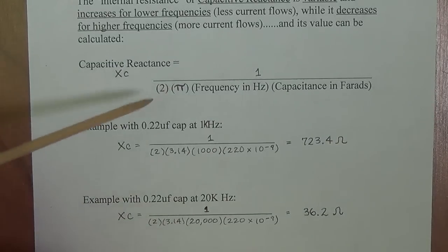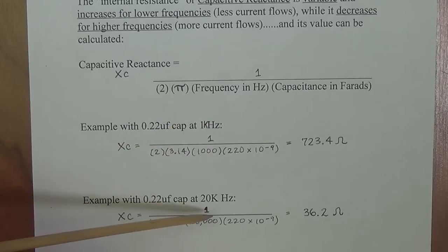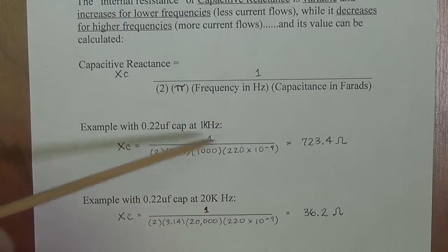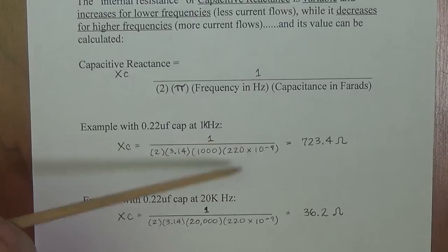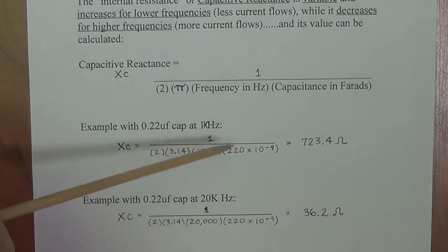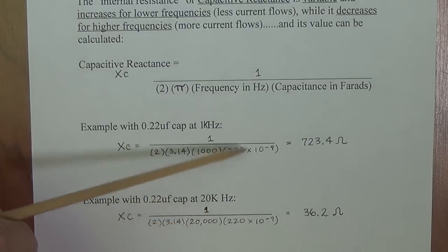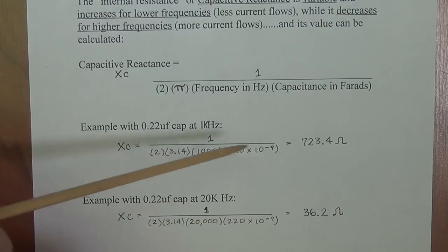We can select different capacitors to allow different frequencies to pass. We can allow them to either pass to the next tube stage or to the output tubes, or we can allow them to pass to ground. Either way, we can very effectively control the frequencies in our input signal that are either helped or hampered.